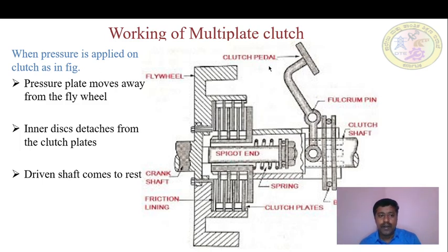So when pressure is applied on the clutch, there will be no transmission of power from driver shaft to driven shaft or clutch shaft. When pressure is applied, this pressure plate will move away from the flywheel by compressing or pressing this spring.